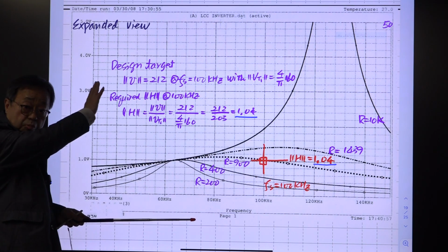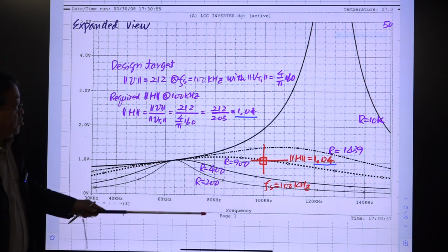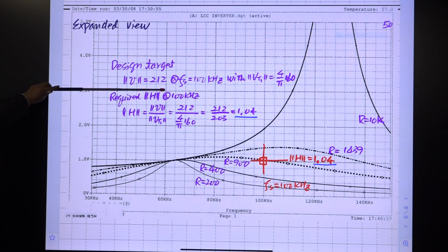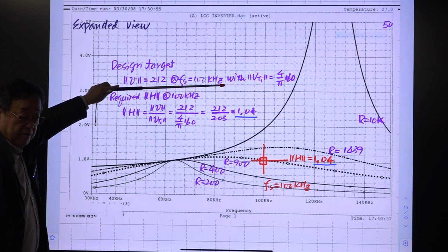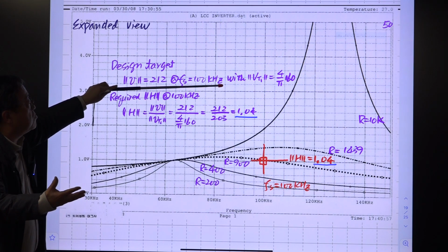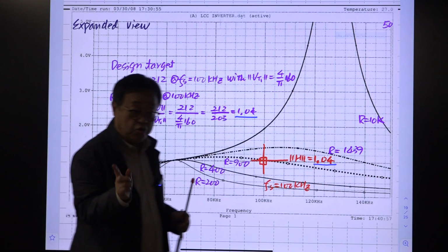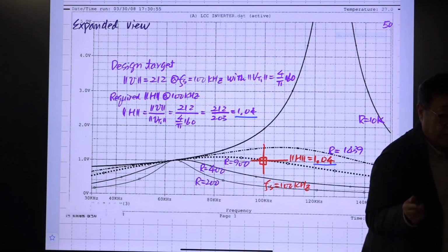We followed all the procedure. The simulation results show that at this frequency, our voltage is exactly at the desired value, at this switching frequency. Okay? And R is fixed. When R is varied or input voltage is varied, then the switching frequency should be changed to make the output voltage constant. For that purpose, we need a feedback controller; frequency control is required.